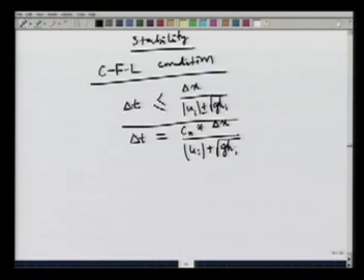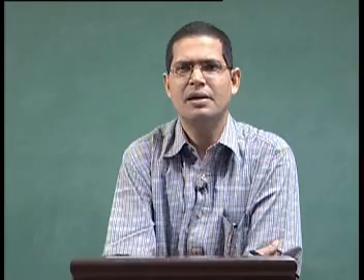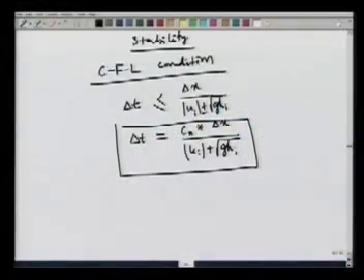Let me explain this. This Courant number Cn is a factor which is less than 1, and this delta x will be given by the user. Ui and hi are known, g is acceleration due to gravity. Based on this, delta t will be calculated. A typical value of Courant number for the Lax scheme is in the range of 0.6 to 0.8. One can use even higher values. One can numerically experiment to decide what value of Courant number is appropriate for the given problem.